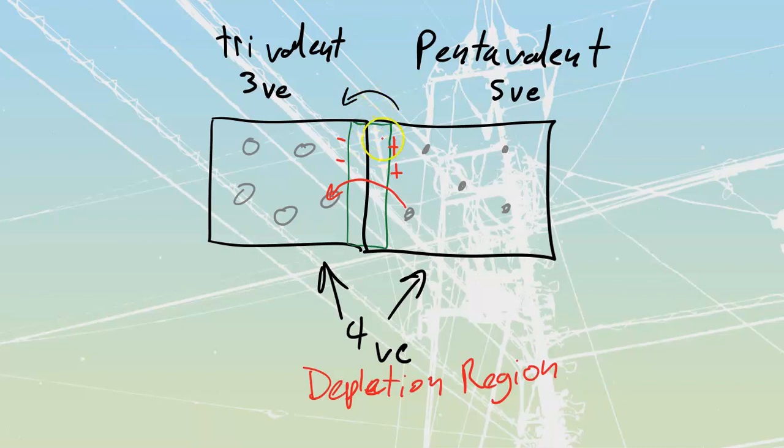That barrier voltage needs to be overcome before we're able to establish current flow through our PN junction. Usually it's just going to require a small amount of voltage, anywhere from 0.5 volt up to 1 volt. We are going to say for silicon, it's going to require 0.7 of a volt. It's just a value we've used through the previous 2 years, and we're going to use it through here as well. And for germanium, it's going to be 0.3 volts. That's the barrier voltage, all we're overcoming with that little voltage drop that we have.